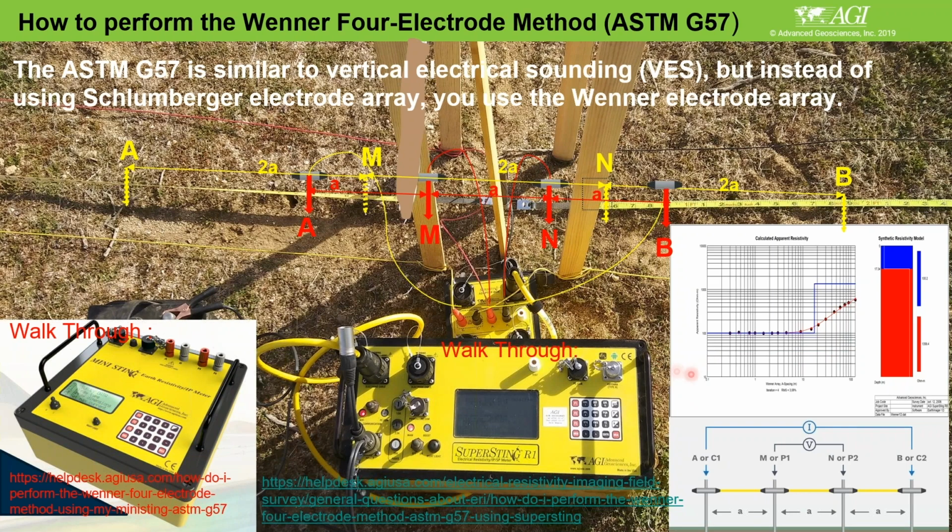The further the A spacing, the deeper you go. Depending on your depth of investigation, you decide where to cut off the A spacing. It's not directly related. The A spacing is not the depth of investigation. Most people confuse that, thinking the electrode spacing is almost the depth of investigation. Actually, your general depth of investigation corresponds to about 52% of the A spacing. If you're doing this kind of thing, this is the typical layout you can use.